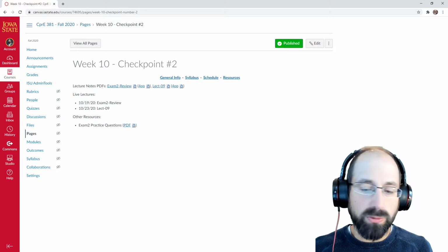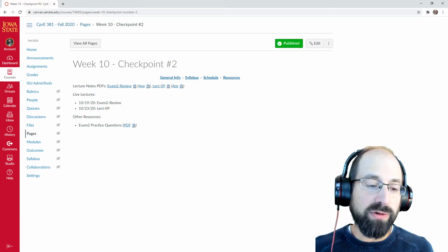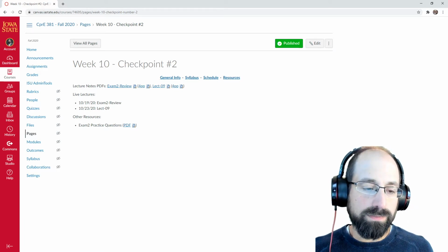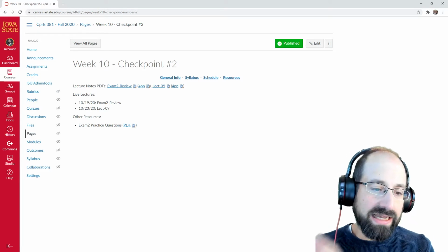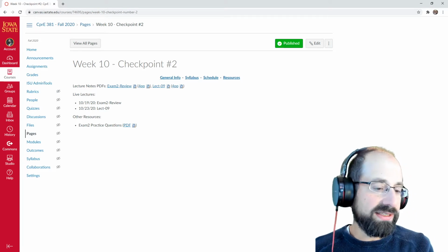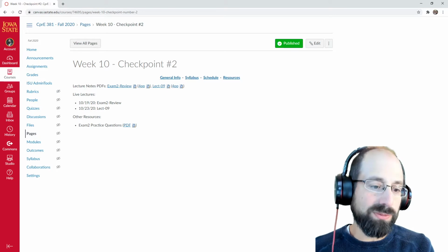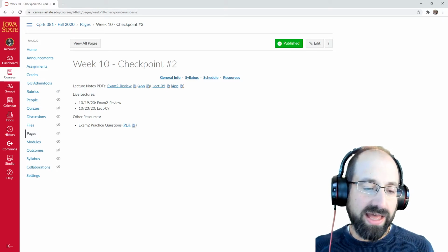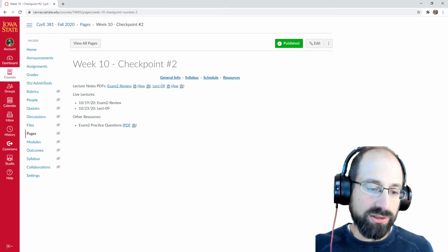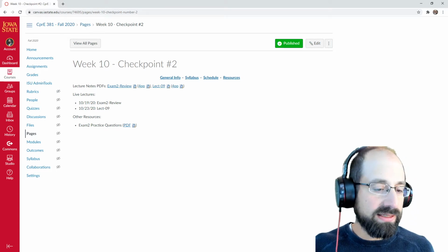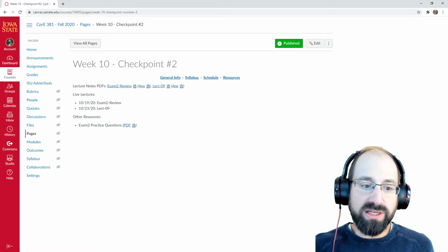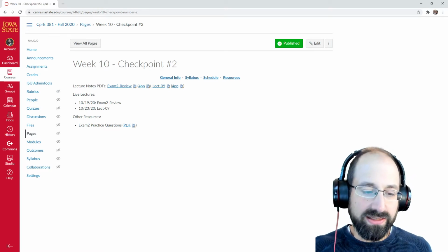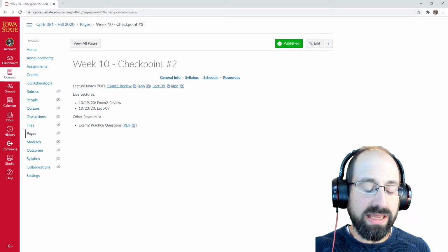But even for our store word and load word instructions, we do have to be very aware that our processor data path is generating a certain address, which is assuming a 32-bit byte addressable address. But then our data memory is this 2 to the 10 entry word addressable component here, and you have to do a little bit of that shifting of bits to get the right inputs into our address field there. And that's something that was already there as part of Lab 4, but I think you would have been just fine in Lab 4 if you kind of ignored that, to be honest, and you could have gotten Lab 4 complete and get 100% on it.